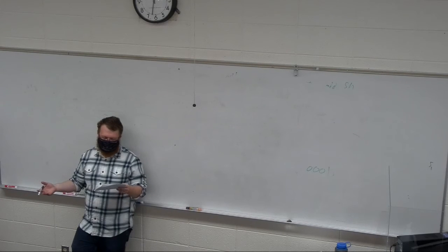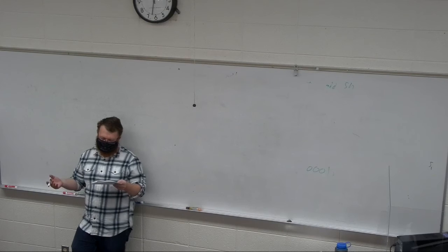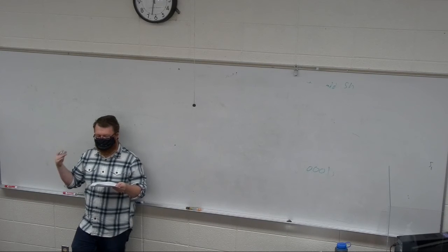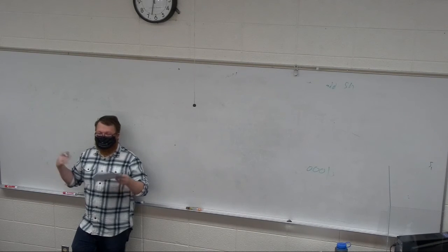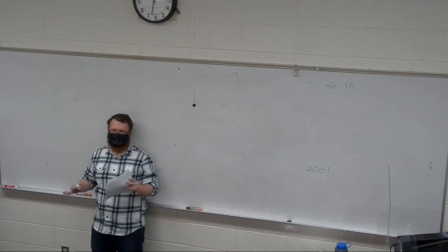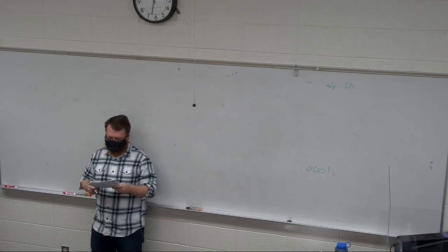and it's a NOR gate. Similarly, the NAND gate is as long as you have not A or not B, it gets pulled to supply, and you need A and B in order to pull it to ground, right? And so some of you wrote AND gate rather than NAND. I'm a big proponent of writing out truth tables for things when you're not quite sure.